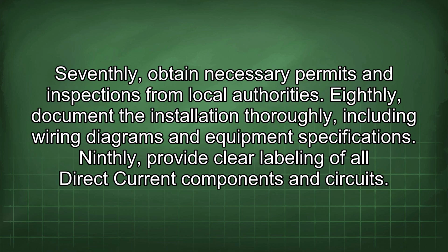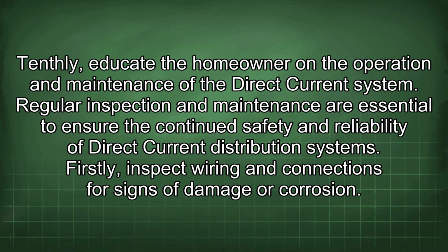Seventhly, obtain necessary permits and inspections from local authorities. Eighthly, document the installation thoroughly, including wiring diagrams and equipment specifications. Ninthly, provide clear labeling of all direct current components and circuits. Tenthly, educate the homeowner on the operation and maintenance of the direct current system.